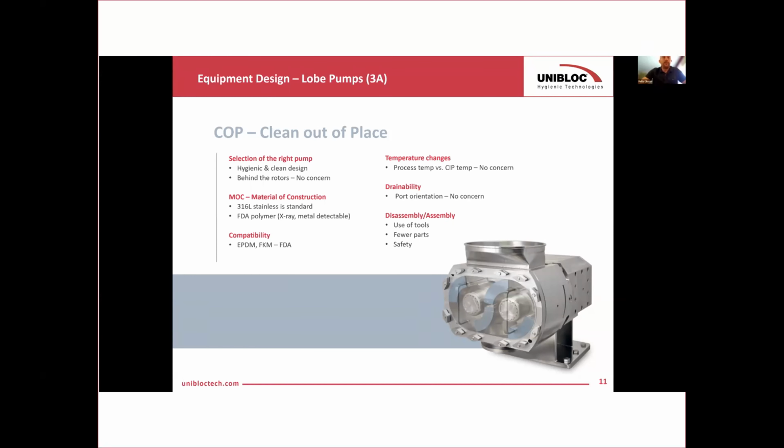Compatibility: EPDM and FKM are still going to be your industry standard and go-to elastomers. On the temperature changes, you're not going to have that in a clean out of place situation, so that concern is now removed. Drainability: the port orientation doesn't matter as much anymore.